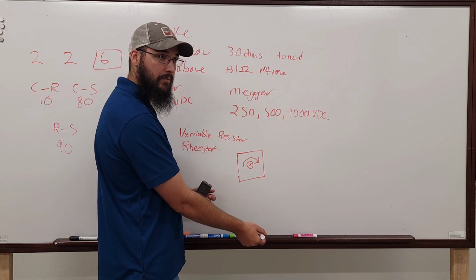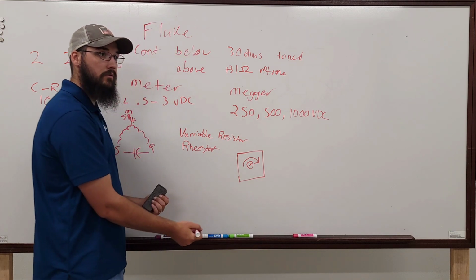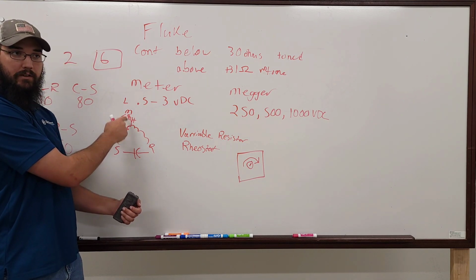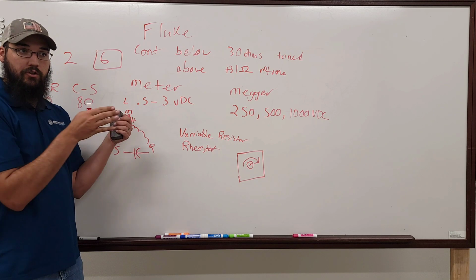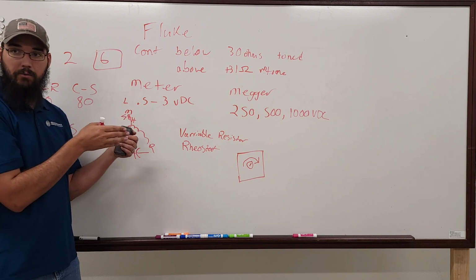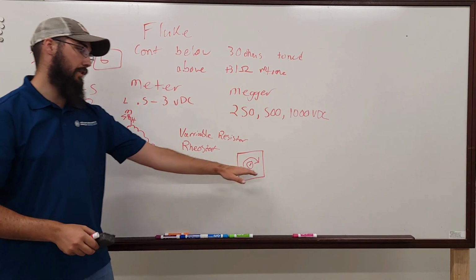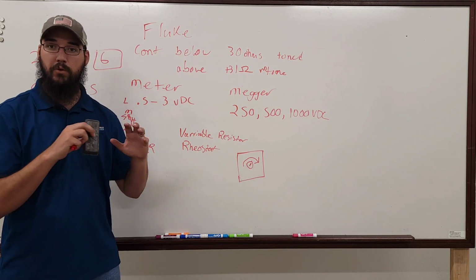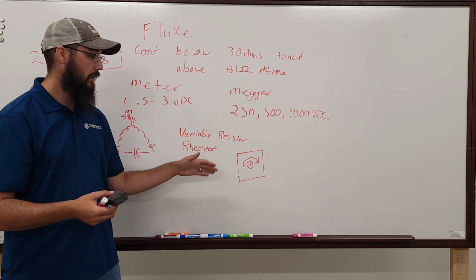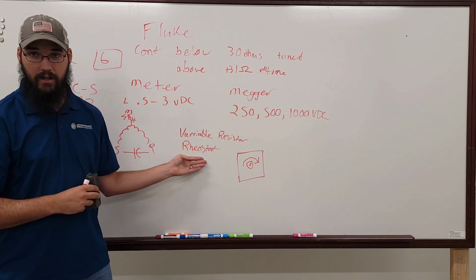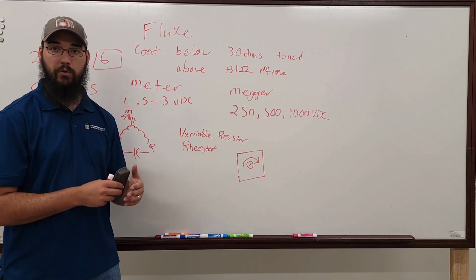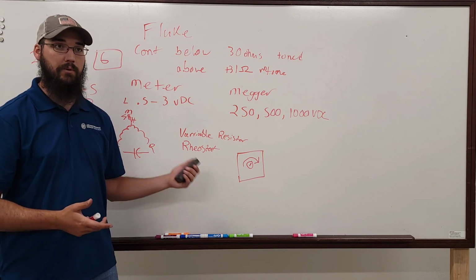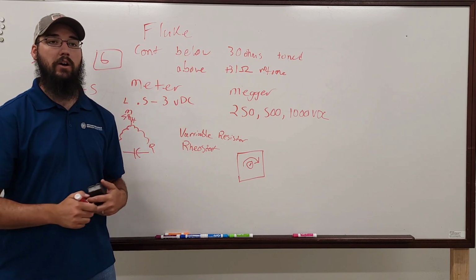So what does that do to the time curve? It doesn't do anything. Instead of having a motor with built-in additional resistance to slow it down through taps, we can get precise control through the motor speed controller, as it's called. The reality is it has a rheostat inside of it, and you're just increasing or decreasing resistance through that rheostat to control how fast that motor turns.